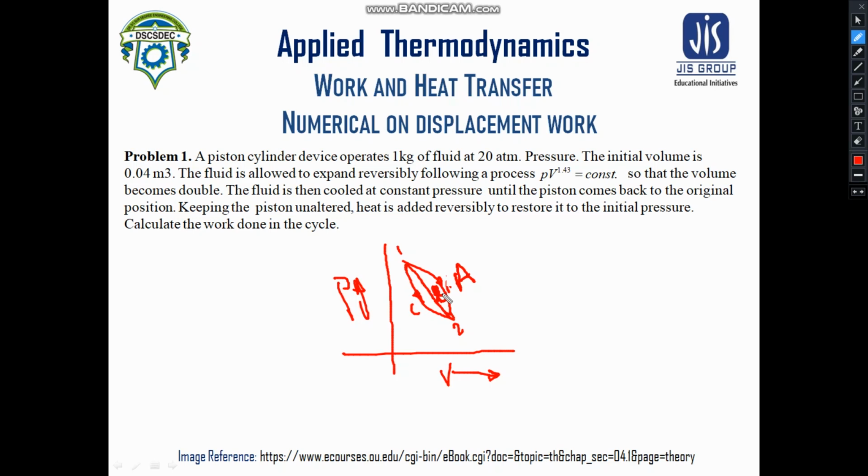But there are certain properties which don't depend on the path. They only depend on the certain state. They have certain values already defined for this state, and the measurement of these properties depends on the nature of the state. And for any cyclic process, there is no change for these properties. Since they depend on the state, for any cyclic process there will be no change.